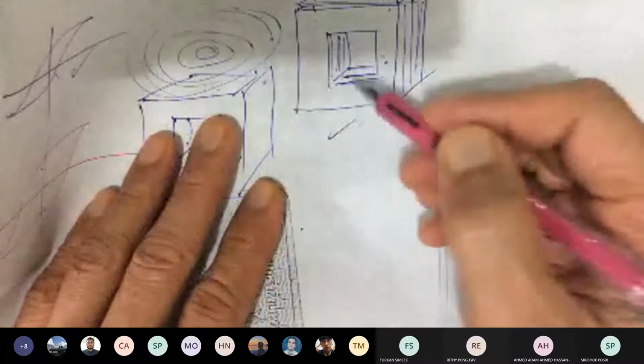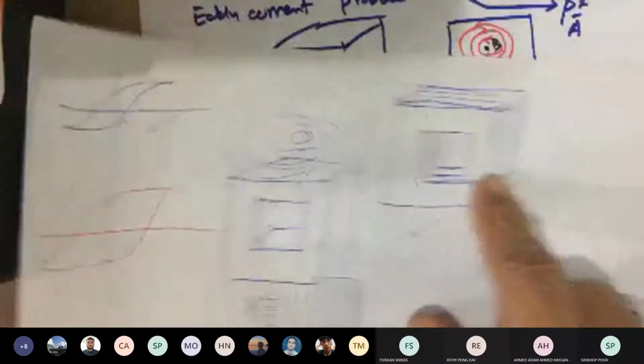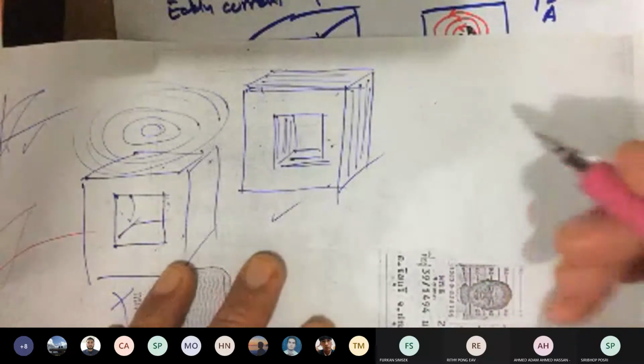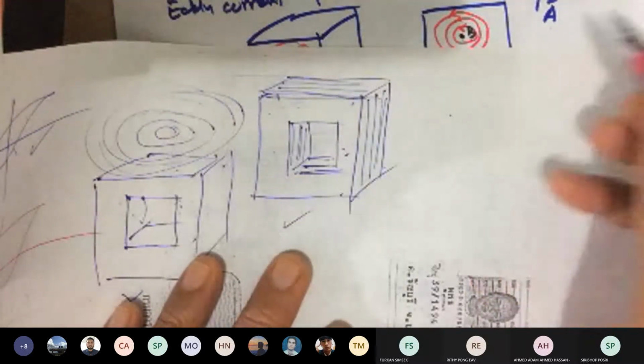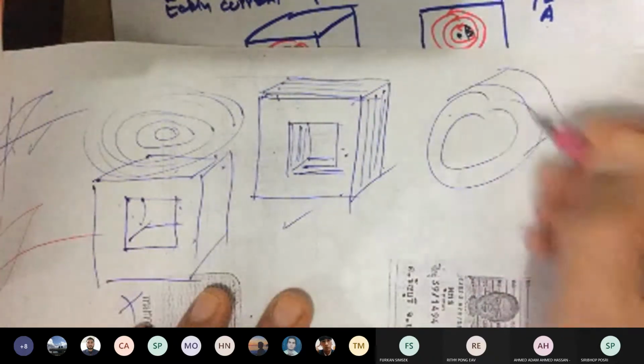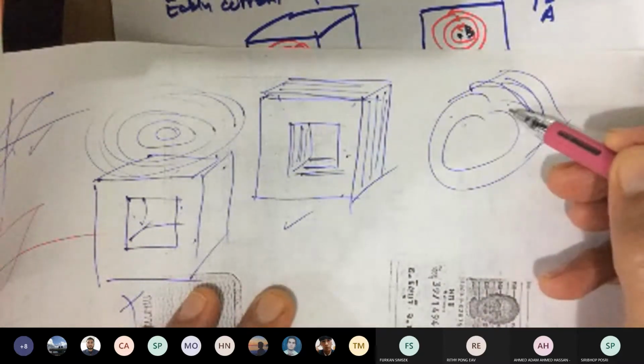each individual sheet. How do you form this core? Actually, you have a metal iron sheet, let's say like this paper. This is maybe too thin, probably a millimeter or less, half a millimeter thick. And then you coat it with enamel or some varnish, a magnetic insulation type liquid. You dip it. Once you have that sheet, you can make it into any shape. You stamp it using a stamping machine, maybe forming a disc. And then you stack that disc to form a cylindrical shape. That's how you make a core of an electrical machine.